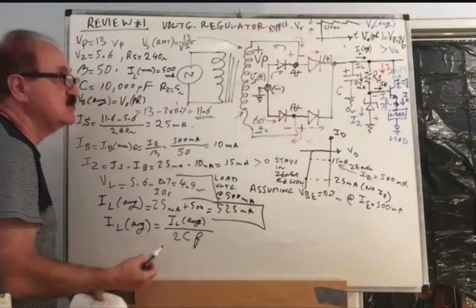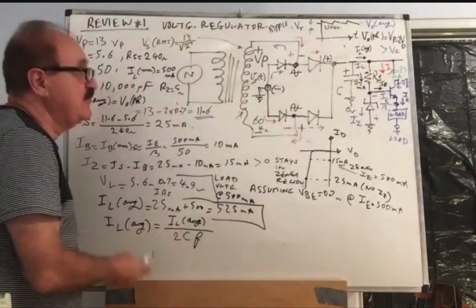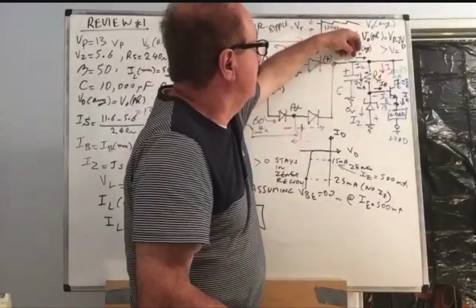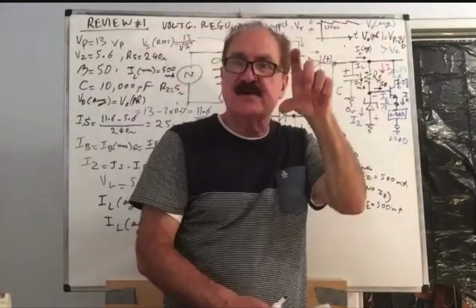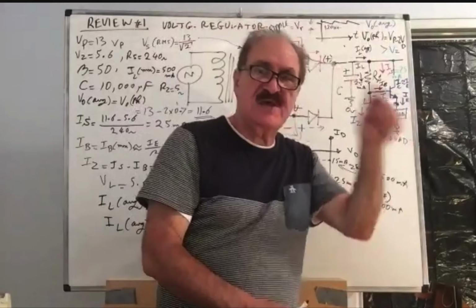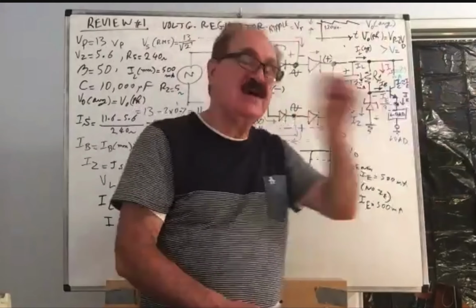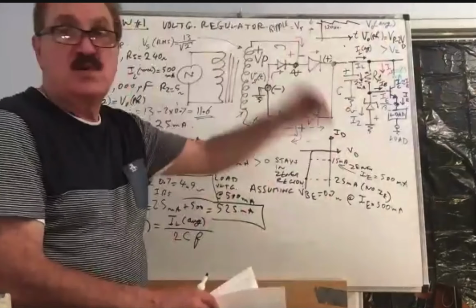Double frequency because there are two cycles in there. IL average is the estimated current that drains the capacitor after every peak. So there's a constant current taken, that's why the capacitor sinks, rises again, sinks, rises. During that sinking course, that ripple will be created.